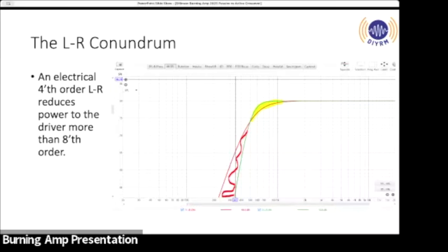And you see the higher order one stays flatter longer and then drops off. There's actually more energy in this little knee than there is all of here, because the dB scale is so brutal in terms of magnitude, right? There's more energy here than there is all of here. And in fact, you've dropped off enough down here where the tweeter excursion is dropping, and I would rather take power out of the tweeter down here or way up here, right, if I'm trying to push my crossover lower.